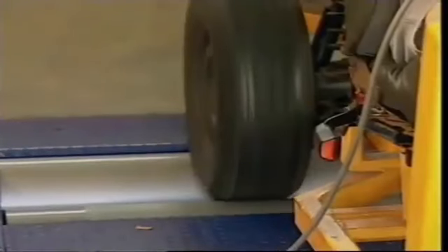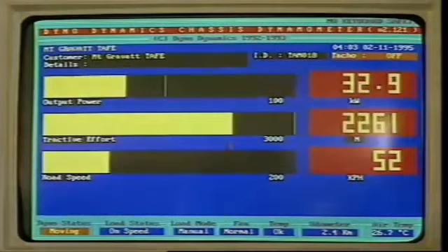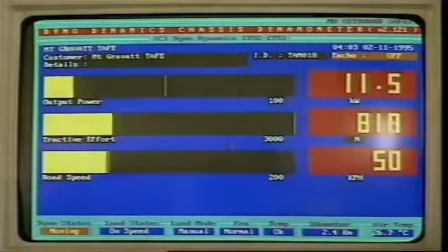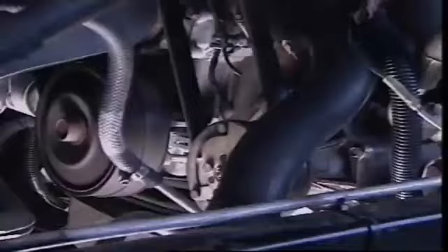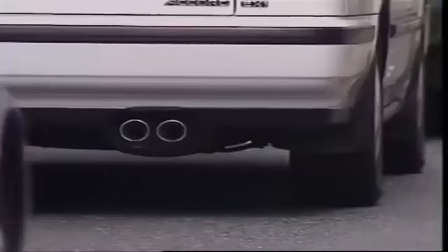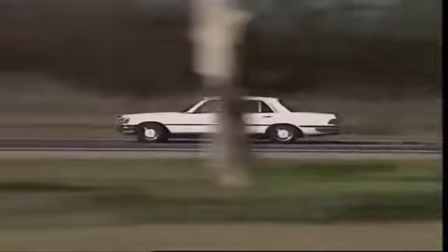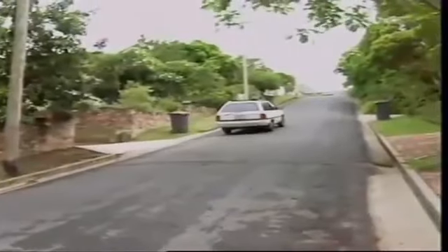Settings are made for various operating conditions according to fuel consumption, engine torque, exhaust emissions, knocking tendency, and drivability. That means, for example, that starting ability can be improved by making timing during cranking depend on cranking speed. Timing at low idle speeds can be set for low emissions, smoothness and fuel economy. For part load operation, the emphasis is on economy and drivability. At full load, it is set for maximum torque without detonation.